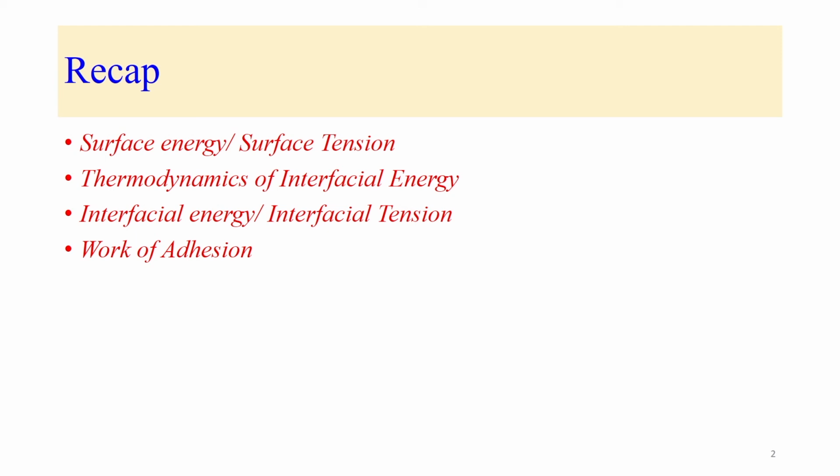So, in today's lecture we will be discussing how we define wettability, or how we define a surface, whether it is hydrophilic or hydrophobic. Then we will see how the wettability and the spreading coefficient are related. Later on we will see the effect of various heterogeneity, chemical heterogeneity as well as physical heterogeneity, on the contact angle or wettability, and in the last we will see contact angle hysteresis.